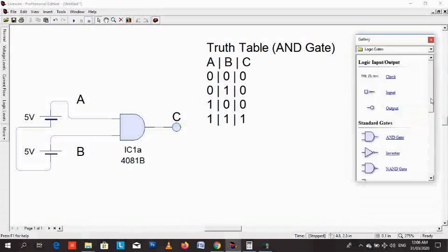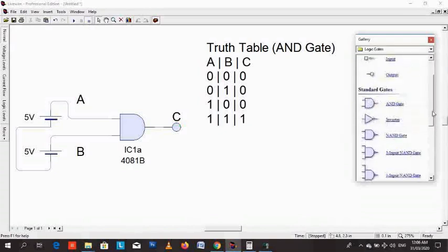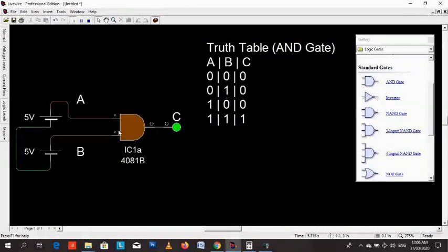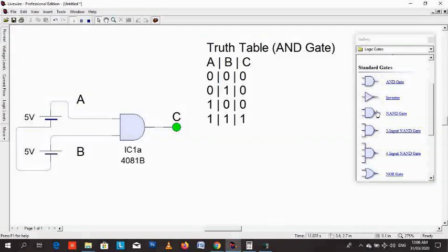Okay, we have to change our gates. These gates don't respond to battery input. It's another bug in the LiveWire virtual library. We see here that it's X, but it's supposed to give us 1. It's giving X, which means that it doesn't recognize that 5 volts. It doesn't recognize the batteries at all. So we have to change it.